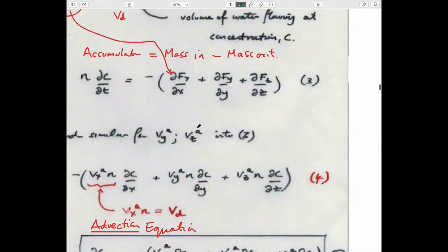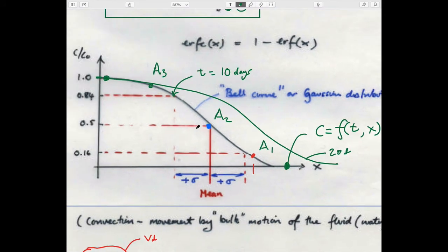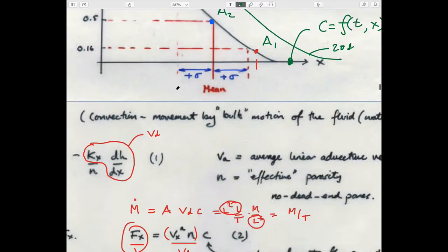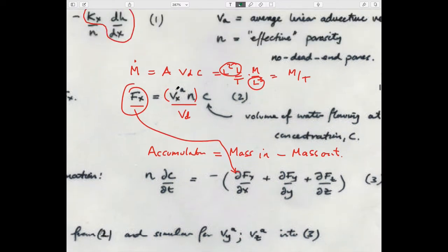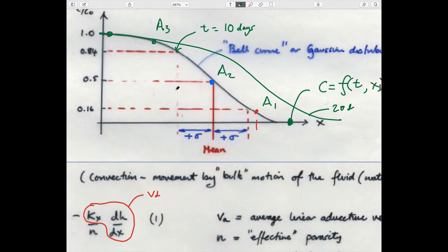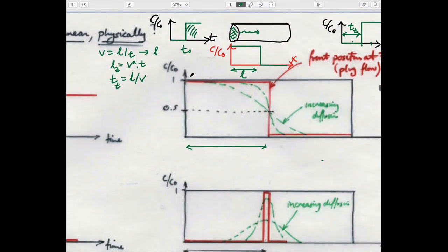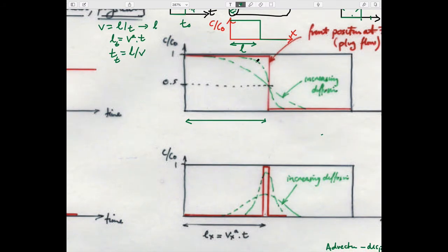Well, we saw that before, the physical manifestation of diffusion was that it doesn't have a sharp front, but it has this flat, canted over profile due to molecular diffusion. And so I suppose if you think in the opposite, if advection is 0, then diffusion will look like this. So what happens if you had advection, which carries the front to some location downstream, but also operating on top of that, you have diffusion acting as well? You'd expect to have this family of curves.